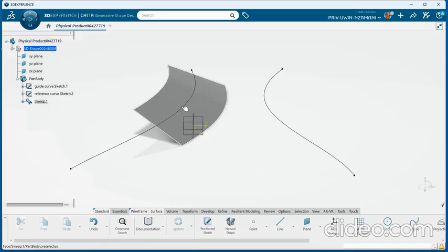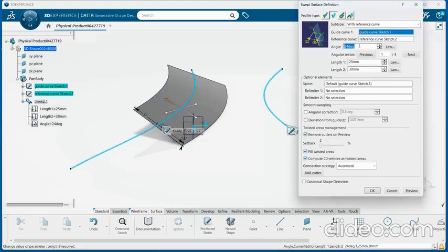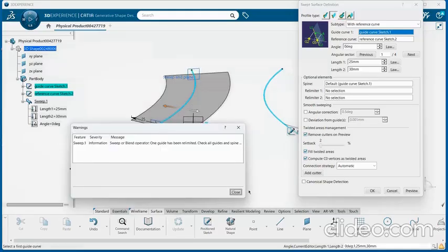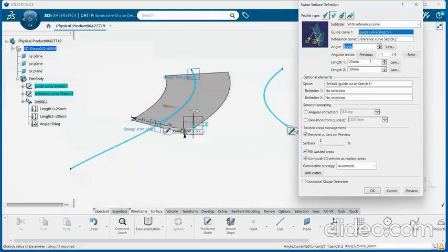Those two points are connected to each other, the intersection point and the point where the spine plane was created. And then it tilts it by the amount that I said. For example, if I go here, if I make this thing 0, see what happens? Okay, it doesn't tilt it. But if I make this thing, let's say, 50 degrees, there we are.